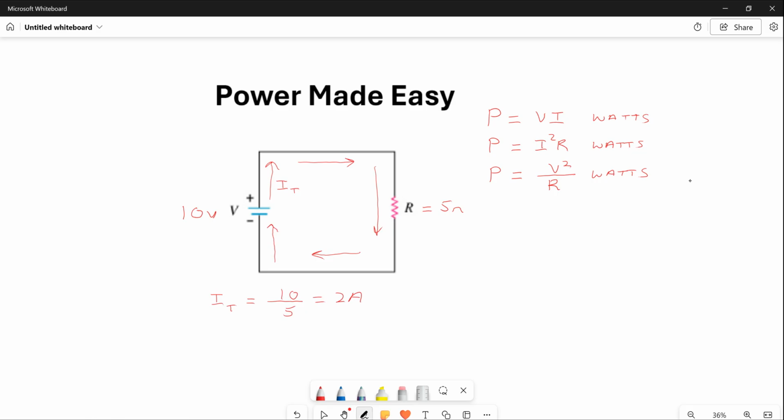It puts a plus up here and a minus down here. That's the passive sign convention. If you look at that circuit, you absolutely know that the voltage source has to supply power and the resistor has to absorb power and give it off in the form of heat.